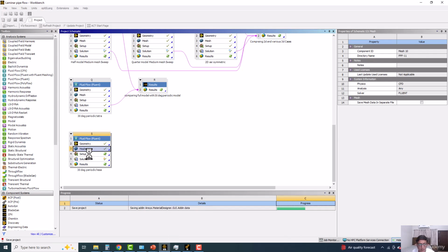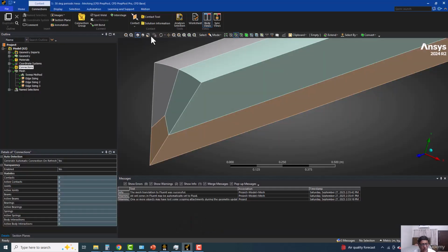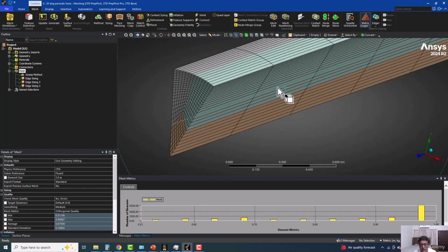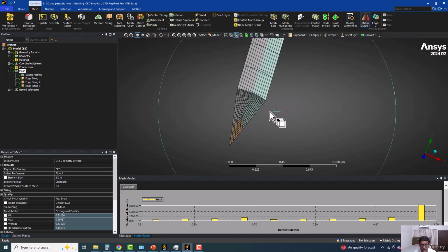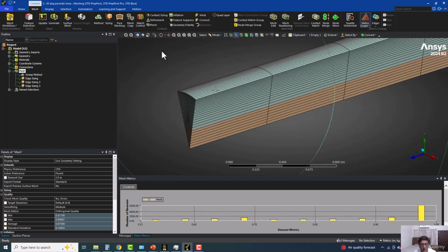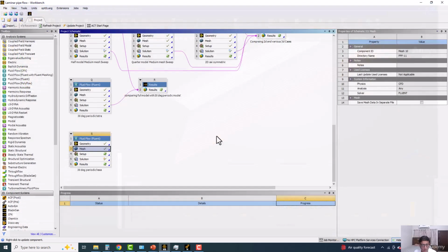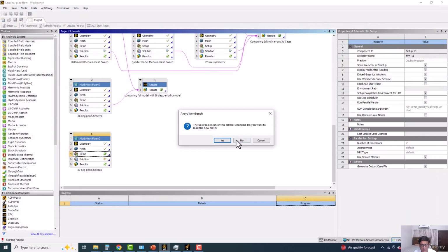So we will do the same thing here, like we don't need the mesh control because although I could use that mesh control if needed, you can use it. But here, because in the Hexa meshing, we have exact control on the sizing and everything ourselves. So whatever size we defined here, same size was also on the other side. So there's no need to use the mesh control. And mesh control, I think, is a good option if required. Okay, here we don't require it, so I'm not using it. Okay, so go to the setup.